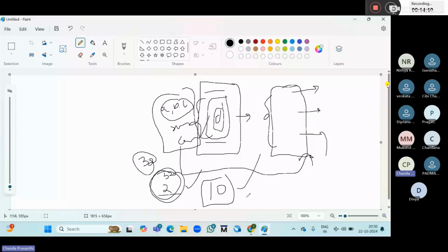Coverage is nothing but a small program, like in OOP concepts. However we use some inheritance, like in randomization or constraints, right? However we write the constraint, coverage is also a small piece of code where we write some bins.